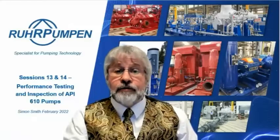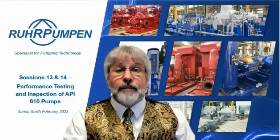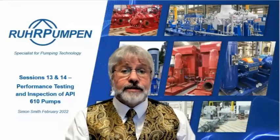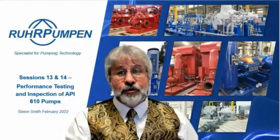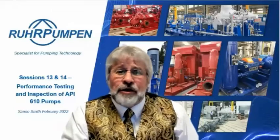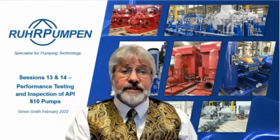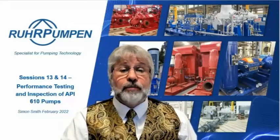And as I said, most pump vendors will have very limited space on their test loops for OH2 and BB2 pumps, BB3 pumps. They'll have very limited space to be able to carry out complete unit tests and to be able to connect it up to the suction and discharge piping. That's going to be the rate determining step. And if it will take a week, that's a week during which that test stand cannot be used. So you're going to be charged quite a bit of money for a complete unit test.